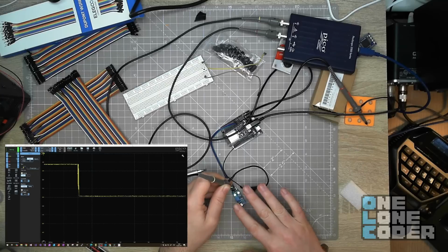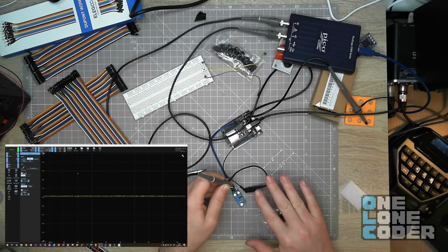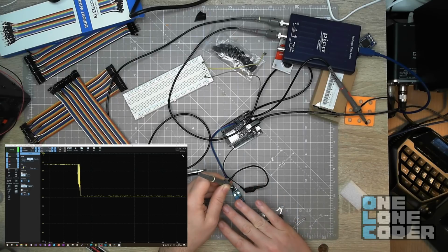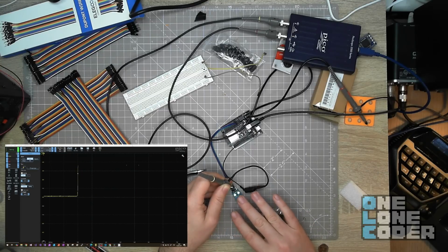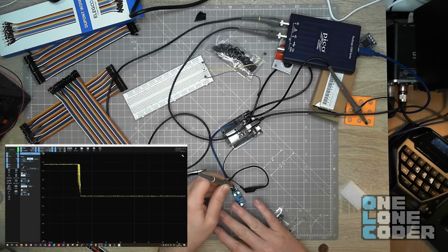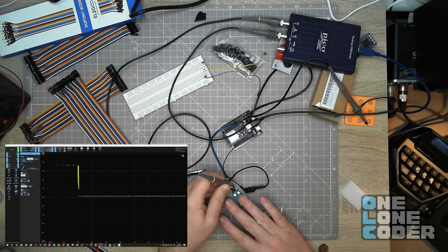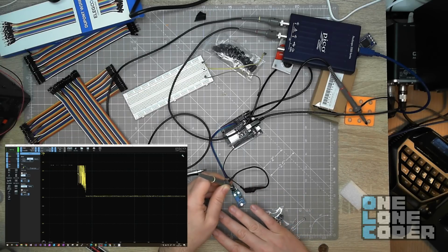There's lots of chatter, as it transitions from high to low and low to high, and that's to be expected. It's because of ambient light, reflections, all sorts of things. The photodiode is very, very sensitive, but the comparator looks like it has absolutely no hysteresis at all, which is a bit sucky. The truth is, I don't think that's going to matter much when we're blasting an LED directly into it in a highly controlled light environment, and that's really what the 3D design is going to provide for us. Interesting stuff.